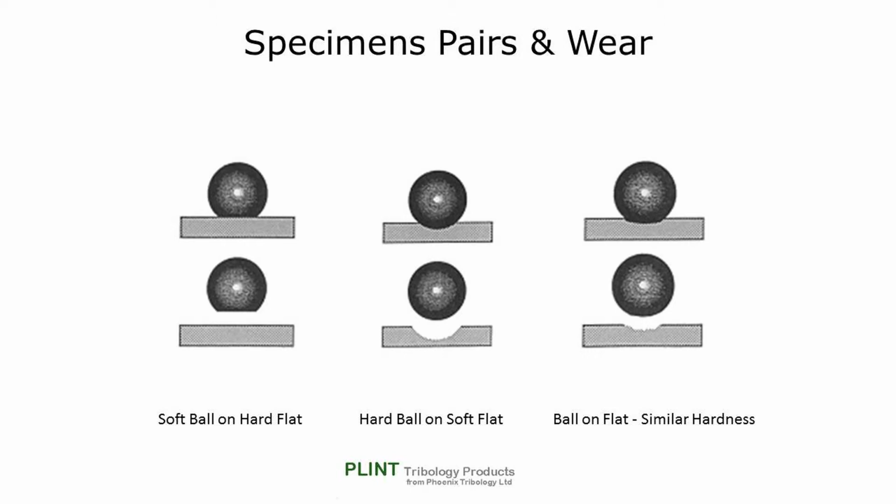With metallic specimens, plastic deformation of the surface and work hardening takes place, thus changing the nature of the material. With coated surfaces, repeated passes by a hardened pin or ball may give rise to adhesion, delamination and subsequent failure of the coating.